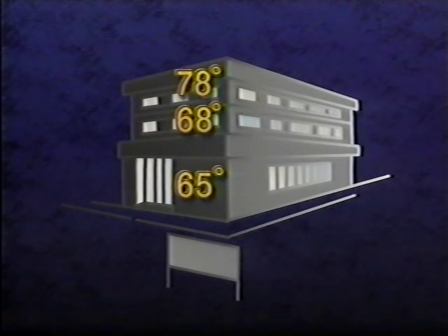Single circuit systems tend to overheat upper levels on multi-level homes and underheat lower levels. With zoned heating, the temperatures can be balanced between levels. Also, if a hydronic system contains two or more different types of radiation, such as baseboard or radiant floor panel, zoning can balance out these temperature differences.